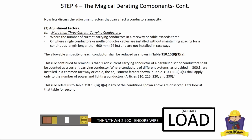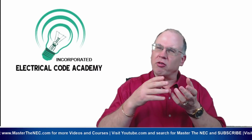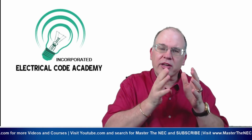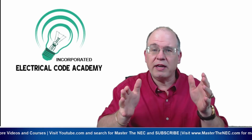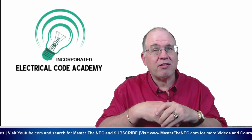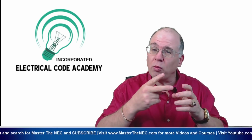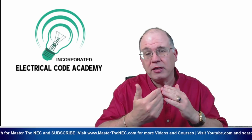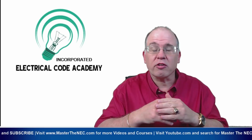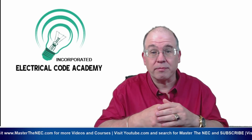So let's give a synopsis of what we're talking about, an overview. If I have that picture I showed earlier where I have 3 raceways and it's a parallel installation, the current carrying conductors in the raceways, all of them in that raceway are going to be considered current carrying conductors. And in some cases, even a grounded neutral conductor, where it's a 4-wire 3-phase and 2 wires and a neutral are coming off, or three wires of a 4-wire Y system, then that neutral conductor is going to carry approximately the same amount, so you're going to count it as a current carrying conductor.